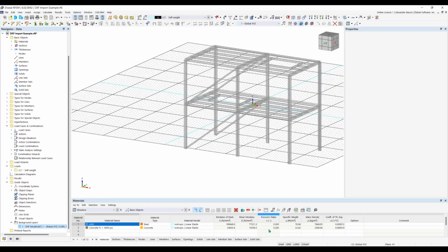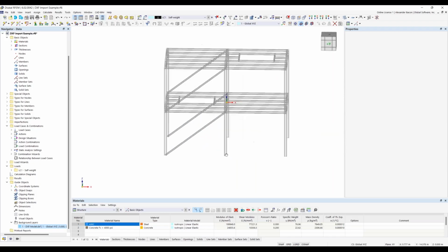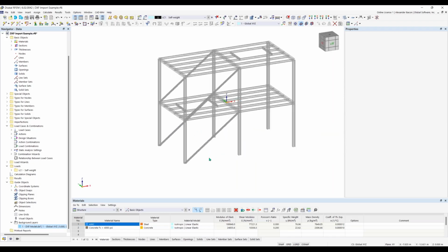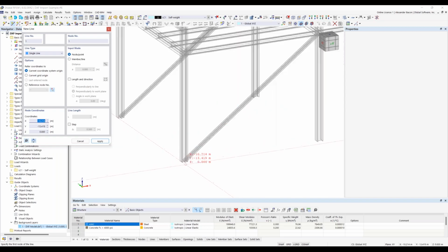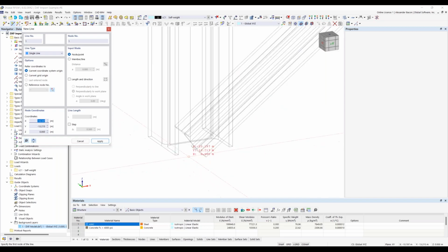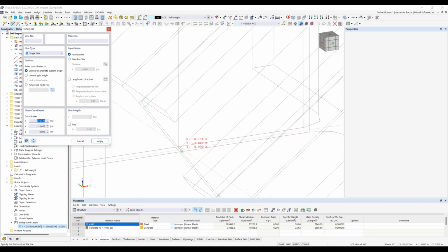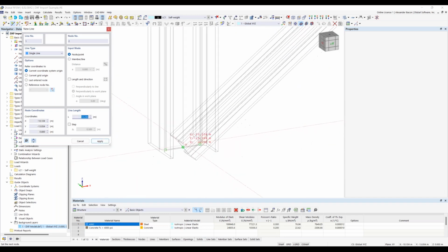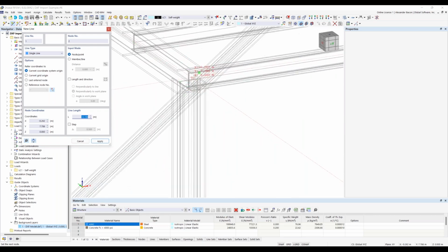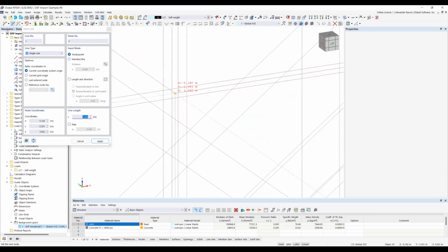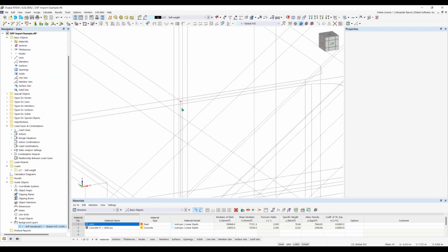So now we can use these background layers to model this. This is similar logic to the IFC file that I showed. And I'll just do an example real quick. So we can draw a line, a center line again. I'm going to use this column again as an example, so I can zoom in here and snap to this point if you have your object snap settings turned on. And then I'm going to go to the top here and I can snap to this point, right click, and